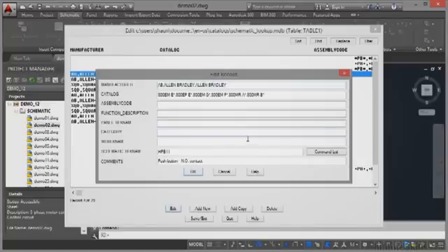Now, because this is a catalog component from a manufacturer, I don't really want to go and edit any of that information because it needs to be there. However, I can add an assembly code, a function description code. If it's on any panels anywhere, I can give it a block name, what category it comes under, what WD block name it has, which is the standard block name that it's used in all of your AutoCAD Electrical drawings, and also the schematic block name. That's the block symbol that comes off the schematic icon menu.